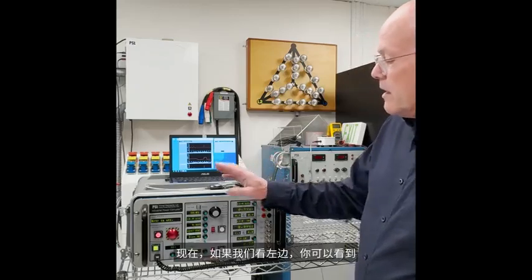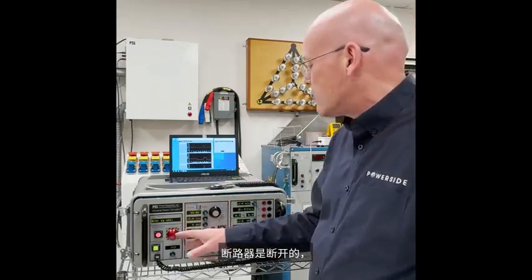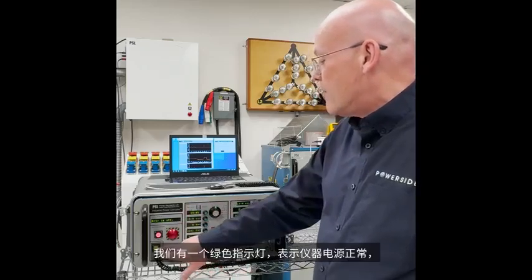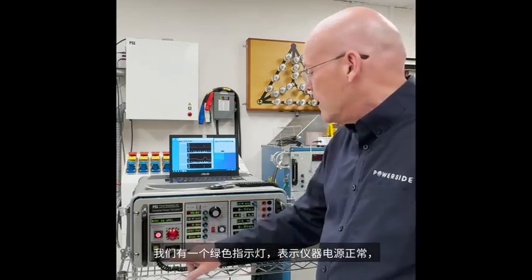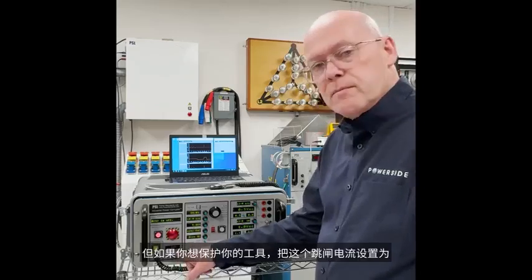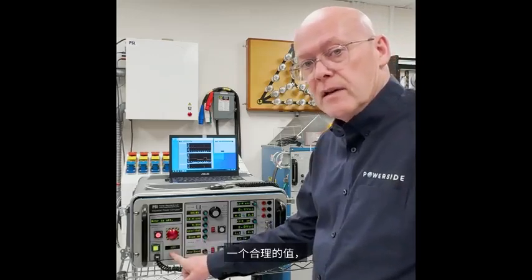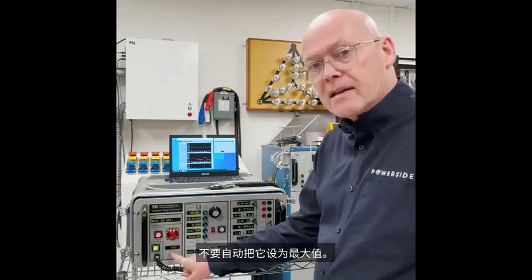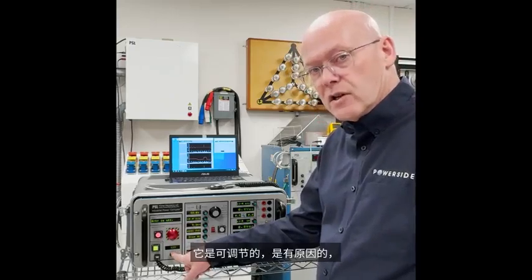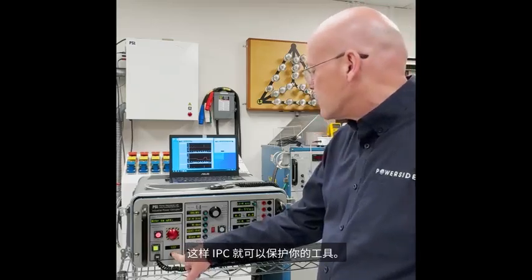Now, if we go to the left-hand side, you can see that the breaker is off. The circuit breaker is open. We've not yet started the test. We have a green indication that instrument power is fine. And here we can adjust the trip current. We talk about it in other videos, but if you want to protect your tool, set this trip current to a reasonable value. Don't just automatically put it at the max. At the end of the day, this is for protection of the equipment. It's adjustable for a reason. And here, this will allow the IPC to protect your tool.